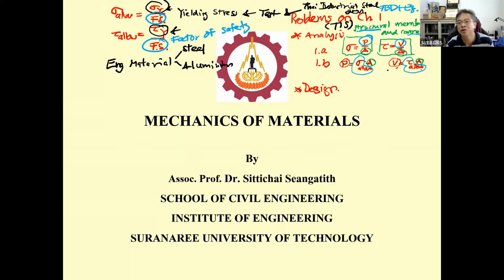So by doing this, you're going to know this also. And then when you compute for the P and for the V, you can use the free body diagram and equation of equilibrium again, changing the internal normal forces and internal shear forces to be what they're asking for, such as the applied loading. So this is the problem to compute for the applied load.